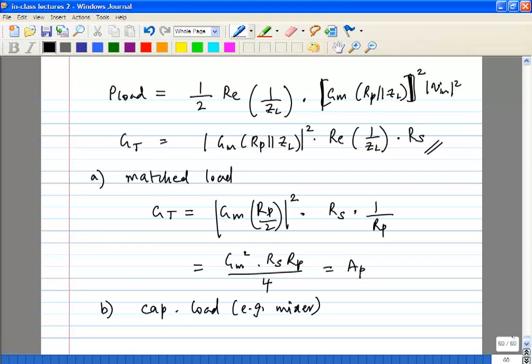It's actually 0, because the input of the next stage, if it's a MOSFET, is purely capacitive, or almost purely capacitive. You will have some kind of gate resistance, which we usually try to minimize anyways. So it's going to be extremely small, which means in such a case, your transducer gain would be 0 or would tend to 0.